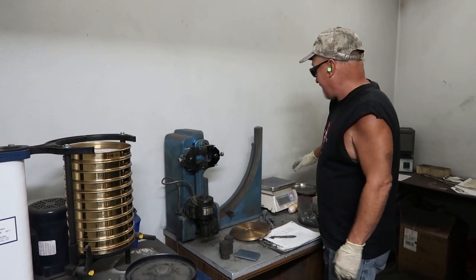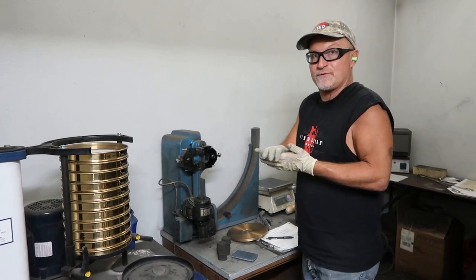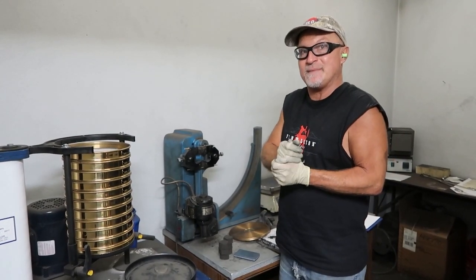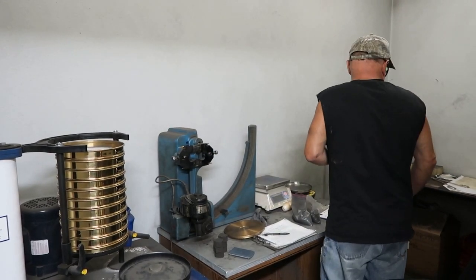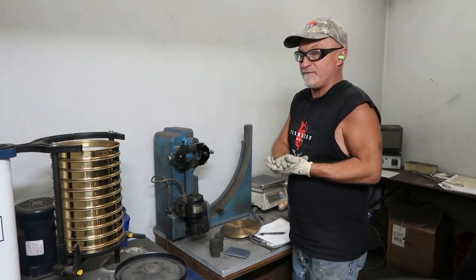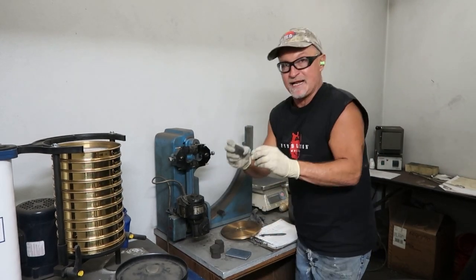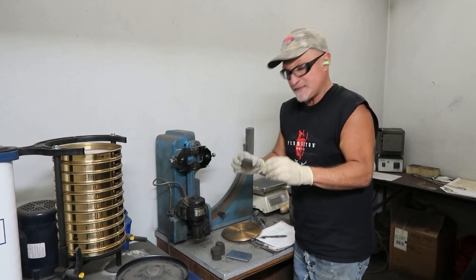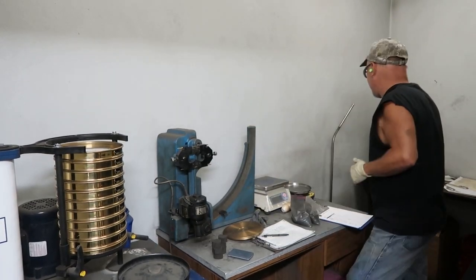Then I'll take a 50 gram sample and I run a magnet through it 3 times to get our metallics level. And then we do have LOIs. I measure up 50 grams for number 1 facing sand, number 2 facing sand, and then I'll take these bones and I scrape to get the 50 grams, and then I put them in this oven right here,